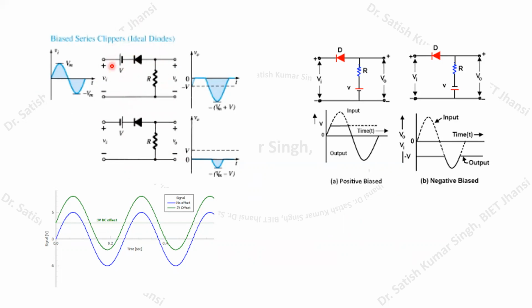Okay, and here we have connected the DC power supply. First of all, you have to analyze whether the DC power supply you have connected is shifting your input waveform in the upward direction or in the downward direction, because it is going to add a certain DC component.